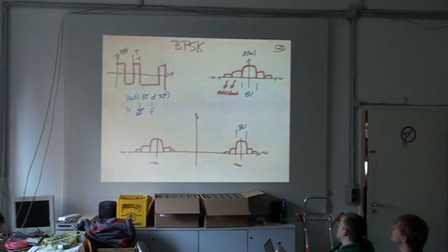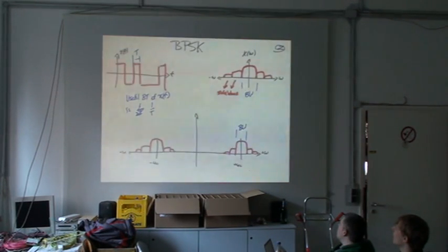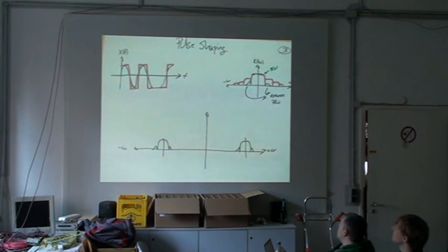But then you see side lobes coming out, and that's because your square wave has sharp edge transitions, and those sharp edge transitions have high frequency harmonics in them that spread out into the surrounding frequencies. Then again, you look at the resulting amplitude modulated spectrum. You have two copies of the original spectrum of the signal, and the same four-way symmetry. The first thing you want to deal with if you're building a radio modem is getting rid of all those side lobes.